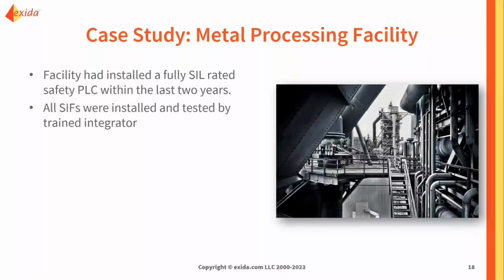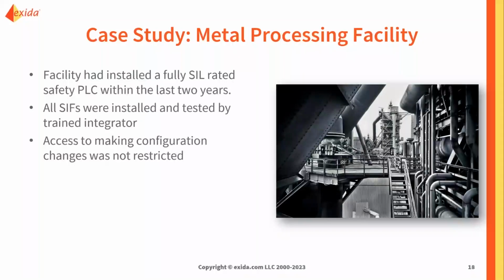And so we start going into the training course, and as we go through each day, we find out a little bit more about the system. The first thing we found out is that access to making configuration changes to the safety PLC was not restricted at all. The accounts needed to make changes were essentially open to everyone, whether it was controls engineers, whether they'd been trained or not, even some of the more involved operators and maintenance technicians who are familiar with the system had the account and could make changes.